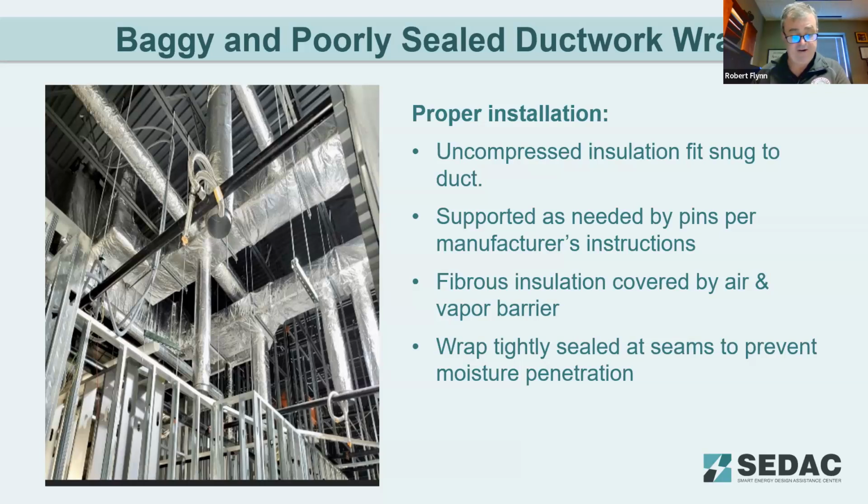So there's different layers, as I told you. As the last slide showed, it's probably a 2-inch insulation with a 3-pound density. The insulation you would see here is a blanket, usually done on concealed ductwork, 1.5 to 2 inches thick, and can have a density ranging from 3/4 to 1.5 pounds density.